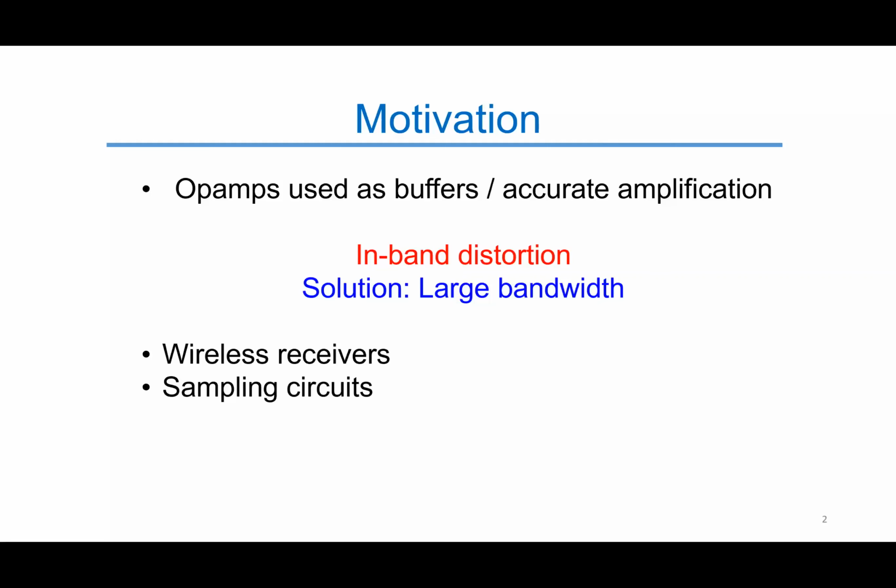It is well known that when used in negative feedback, the distortion performance of the loop improves by the factor of the loop gain of the negative feedback loop. So, if the input signal has a certain bandwidth, we need to ensure that the loop bandwidth is larger than the bandwidth of the signal itself in order to keep the distortion in check. This obviously has few repercussions.